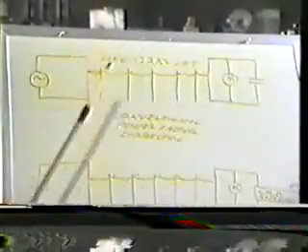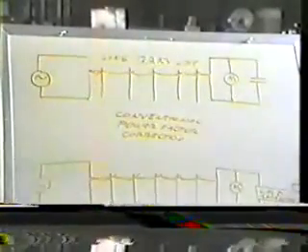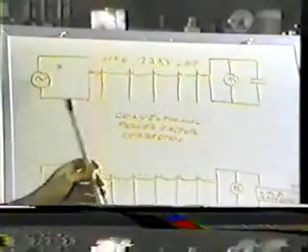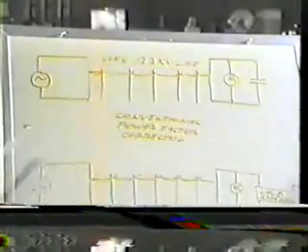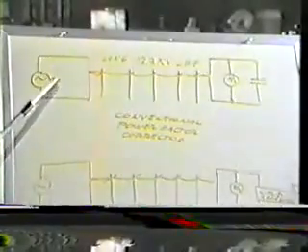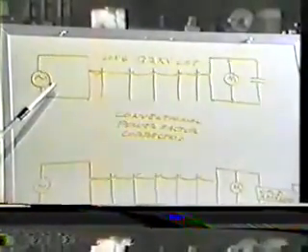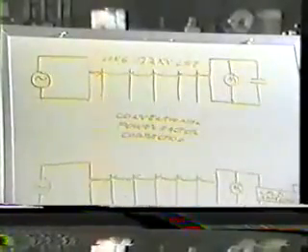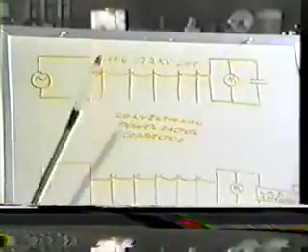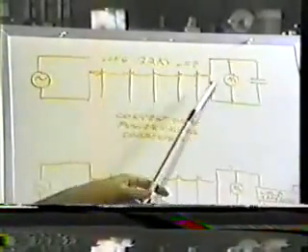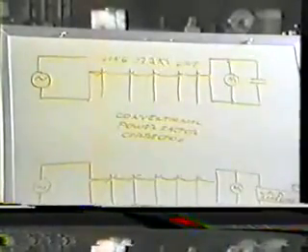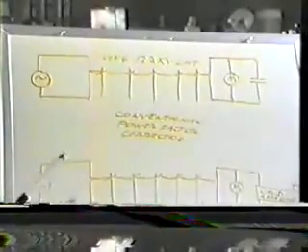The capacitor will resonate with this magnetic energy in the wire and cause the voltage of the system to rise as you go to the load, which of course is quite different than in normal DC circuits. So it's not uncommon in an alternating current power system that the voltage will start off nominal at the generator, which is usually 13.2 kV, and go up to 13.8 or 14, and if you remove the motor, it would go up to infinity. What happens when the voltage gradient rises at the plant is that the kilovolt ampere reactive hour meter will start to turn backwards, which usually causes trouble with the power company.